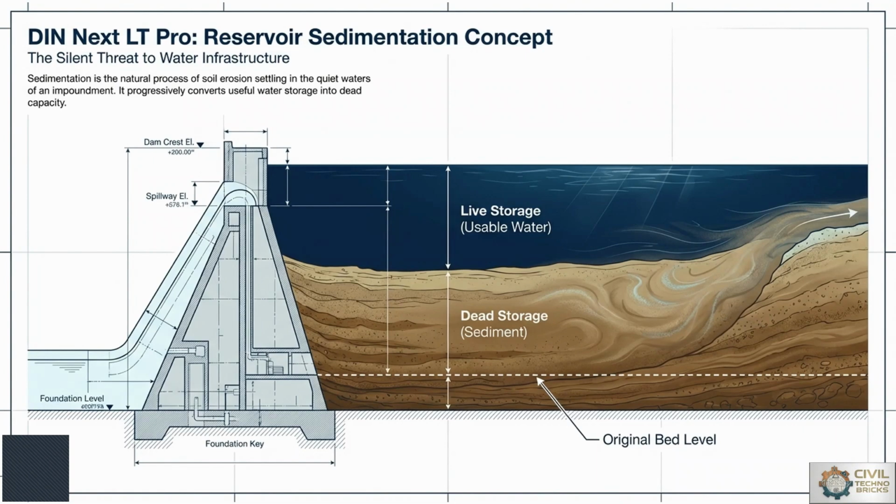By using GIS tools, we can model the entire catchment area to identify the erosion hotspots, meaning the areas contributing the most silt or accumulating large amounts of sediment, allowing us to plan mitigation strategies like check dam construction or afforestation more effectively. We have to increase tree plantation to minimize the erosion of materials flowing with the runoff to the nearby catchment.